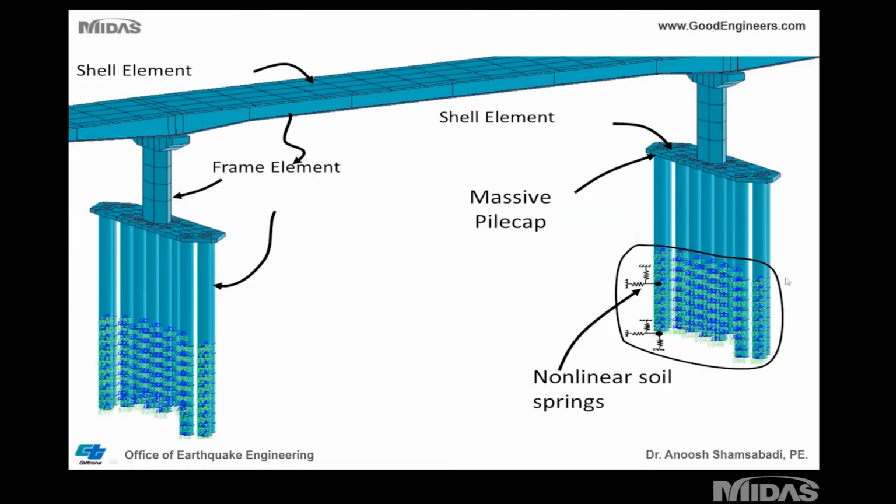Again, nonlinear springs, a closer shot of the piles. These are nonlinear springs attached in Midas. One thing about the new version of Midas, I don't know for those of you who are using Midas if you have the latest version or not, but you can basically develop your nonlinear springs outside Midas and copy-paste them in Midas. It has a new option now that you can develop your nonlinear springs, tension and compression, and easily copy-paste them in Midas and then attach them at every node. You can attach those springs very easily.